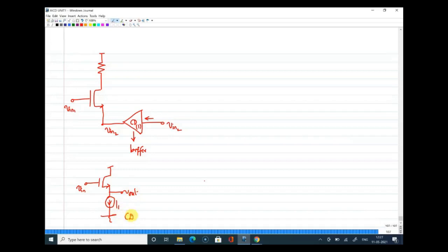Right. So plugging in the same series stage here, this is my initial transistor where I have connected V in 1. Now to this point, I need to connect a CD amplifier here, let's say with a constant current I. This is I. Now this is V in 2. So at this point you will get V in buffered and that will go to this.